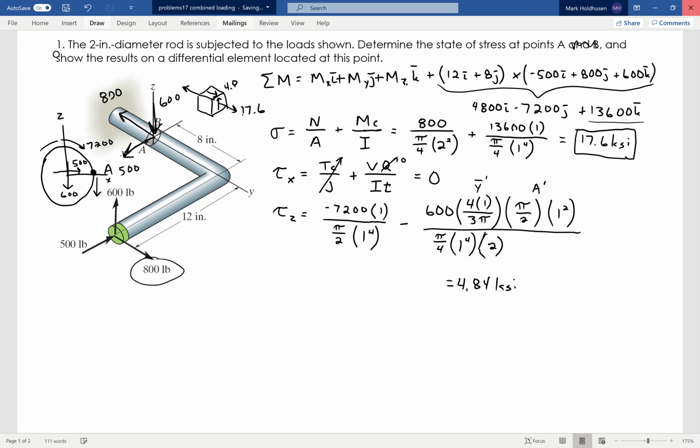Again, I'm much more interested in understanding what direction things are going than in whether you get positives and negatives. Tension and compression is usually a bit easier to visualize. For the shear stress, remember, I'm looking at the back side. So when I'm talking about things going down, I'm talking about down on the back side. On the front side, because I have to keep it in static equilibrium, it's upward. So that is what the element will look like. That's what those values will equal. And you basically just have to add together both components that create normal stress and shear stress to figure this stuff out.